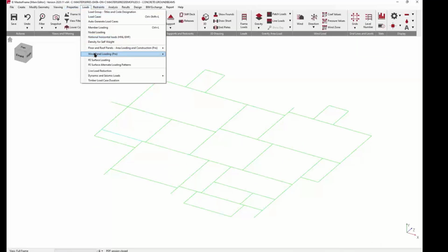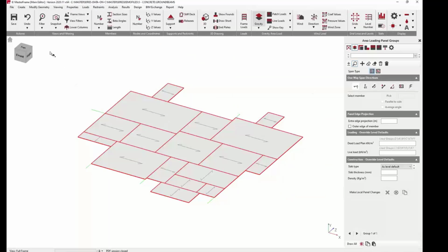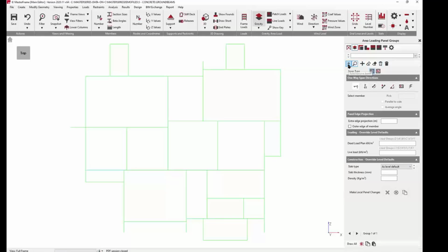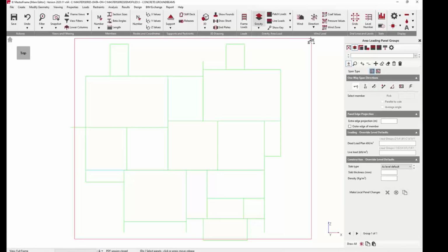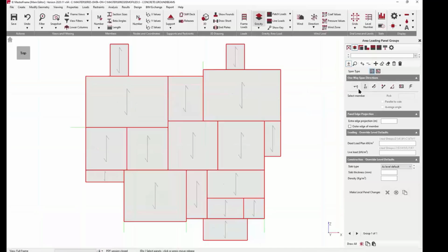The next stage is very straightforward, is adding the panels. And what I've done is I've added all of these panels, and I've added them as spanning in the x-axis. But what I then did was I overrode these ones here to span in the z. So if I just delete this for a second and add a new one, and then just window all the frame, and there we go. So we're all spanning in that one direction, be it X or be it the Z.